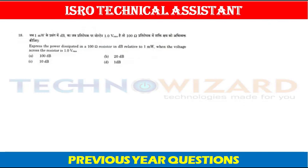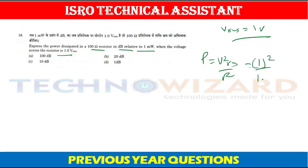Question number 18. Express the power dissipated in a 100 ohm resistor in dB relative to 1 milliwatt when the voltage across the resistor is 1 volt RMS. Okay. Therefore, Vrms is given as 1 volt here. Okay. And we know that power is equal to Vrms square upon R. That is 1 square upon resistance is 100. Therefore, this is equal to 1 upon 100. Okay. This is output power. Input power is given as 1 milliwatt. That is 1 upon 1000.